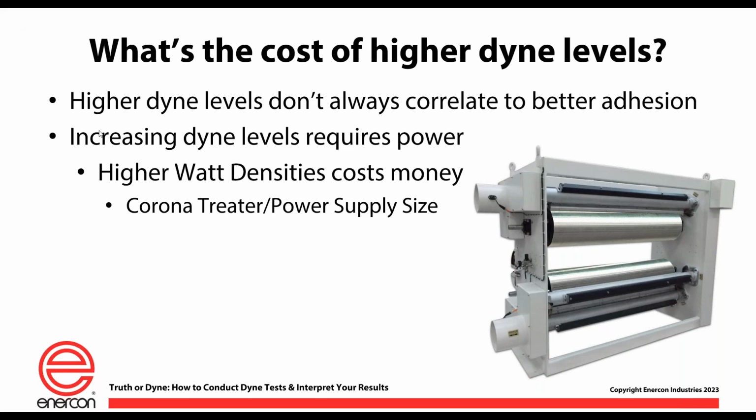I've had customers, film extrusion customers, say to me, I have this order for a truckload of film. The client insists that the dyne level of the film's got to be 50 dynes. So I need to buy a treater that's good for 50 dynes. Well, like I said earlier, I'm not telling you there isn't any, but in my practical experience, I don't know of any coating or adhesive or ink on a general converting application that requires 50 dynes.